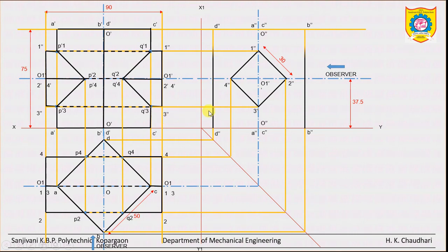Okay, now in the side view, similar to this B and D edge, when we observe this intersection from the left side, the edges B and D are not taking part in intersection, so B and D will be thick in side view also, so we have drawn thick. Similarly for the top surface and bottom surface, there is no intersection, so draw them also thick.